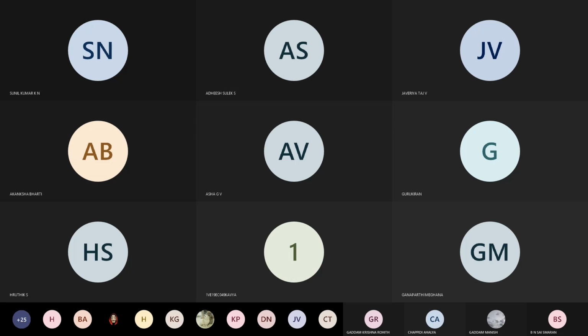In this case I am going to have 3, whereas if I connect n input voltage sources here, the output voltage should be equal to what? 1 by n times the sum of the input voltage sources, VA plus VB plus VC. That type of circuit is called an averaging amplifier circuit. We are going to see what conditions have to be there. If I get the average of the given input voltages as the output, then that type of circuit is called an averaging circuit.